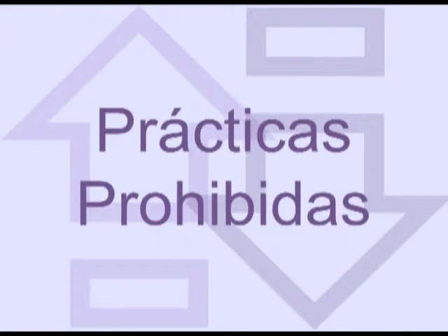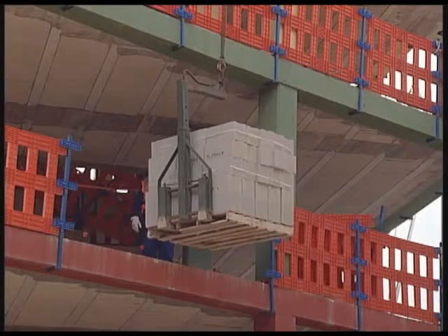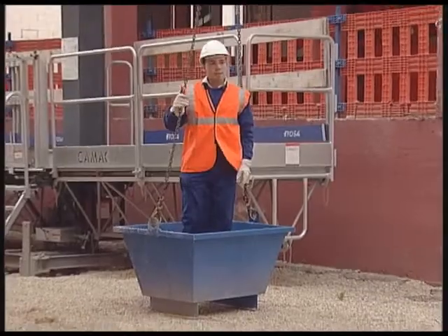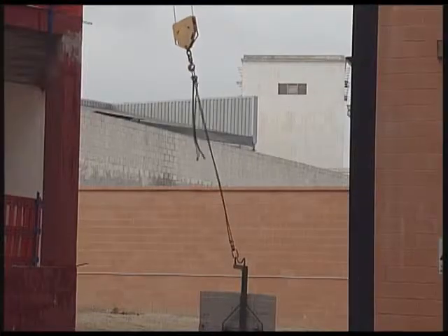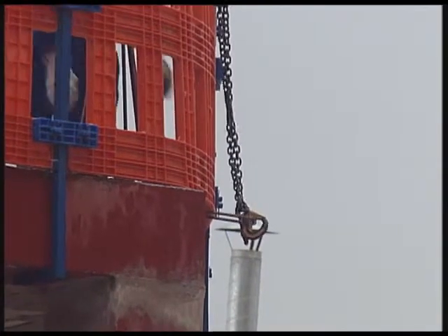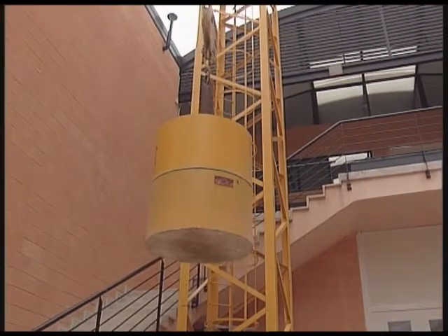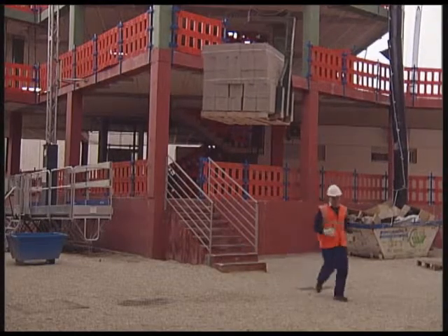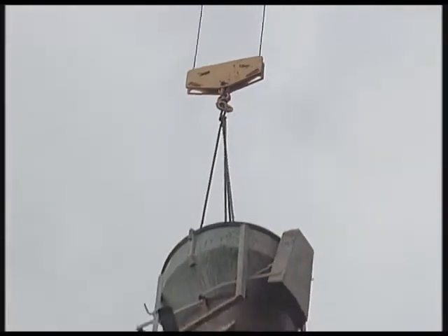Forbidden operations. It is strictly forbidden to swing loads, to transport people, to lift a load at an angle, to lift fixed loads, to lift loads over the permitted maximum height, to suspend loads over personnel, to leave loads hanging from the hook without the crane operator being present.